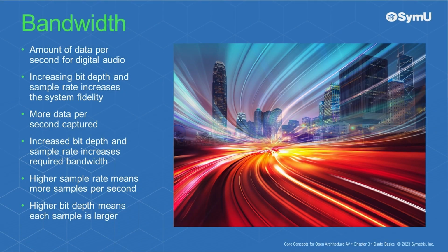Bandwidth is the amount of data required per second for digital audio. Increasing the bit depth and sample rate increases the fidelity of a system, with more data per second being captured. Increased bit depth and sample rate also increases the amount of bandwidth required to transmit the signal. A higher sample rate means more samples per second, and a higher bit depth means that each sample holds more information, making it that much larger.